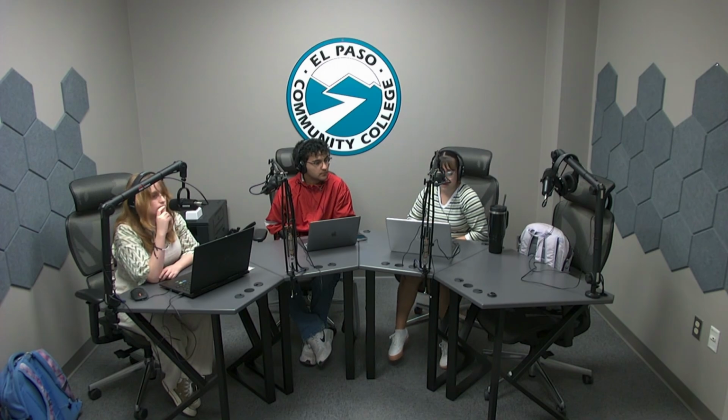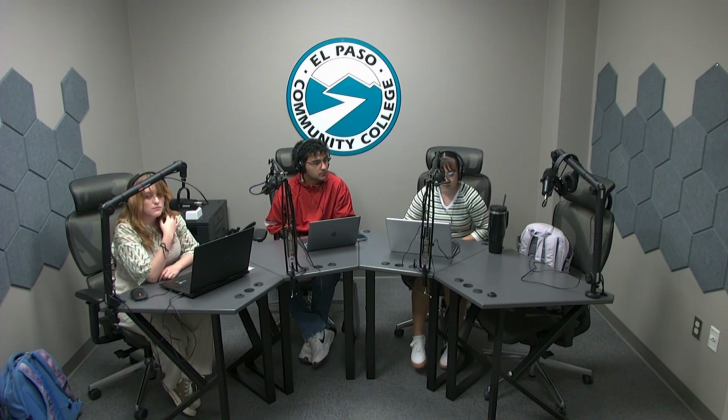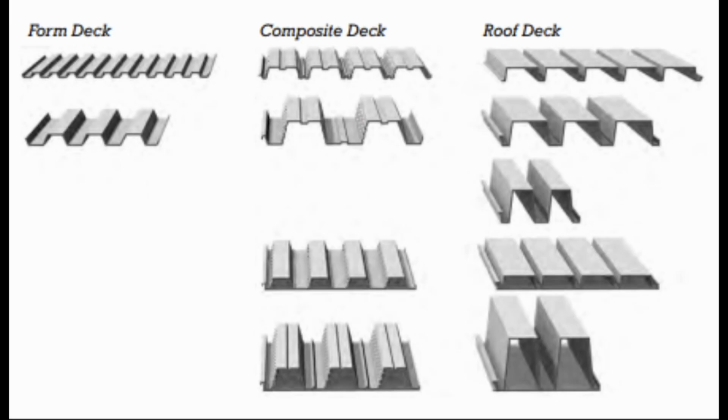But there's also metal decking, which has 3 types. First is form decking, a metal decking that acts as formwork only. And the composite metal decking is designed so that once the concrete has hardened, the two materials beneath act as a unified element or composite floor slab.